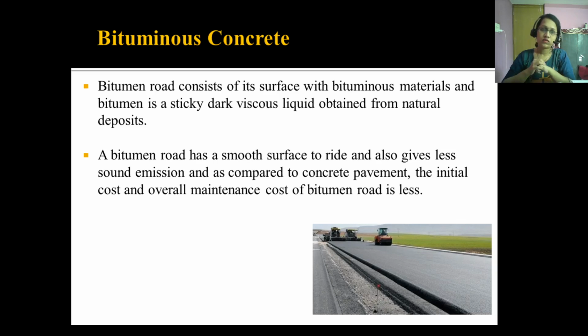Based on the surface area of the aggregates and the technique of the construction, the optimum binder content may be determined. Another problem associated with the construction of the bituminous pavement is the control of the proper viscosity of the bituminous aggregate mixtures during mixing and compaction operations.